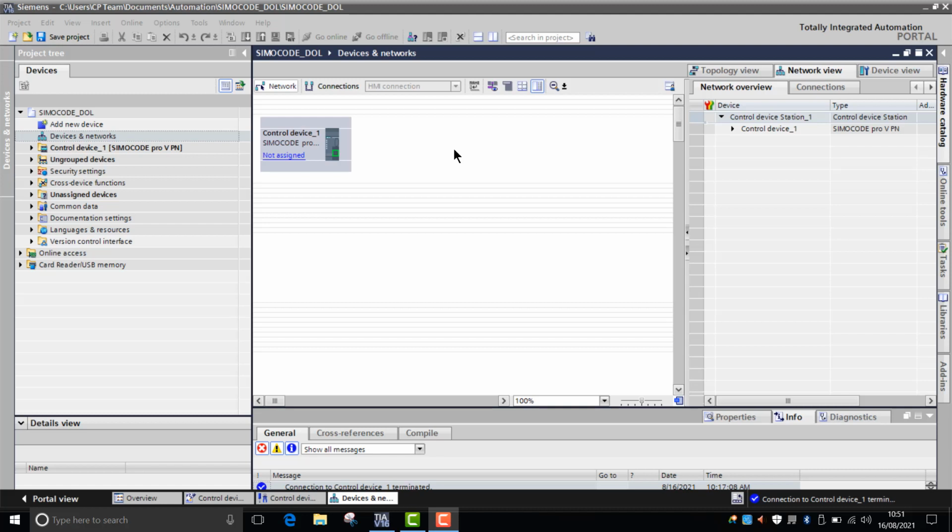Another feature is that the device also monitors hysteresis discrepancies in this feature. You could utilize that for an underperforming motor. If you have a discrepancy in hysteresis, you might have a low efficiency motor. You'll have low torque and a low power factor. All of those conditions are undesirable in a motor application. So I'm going to jump in now and show you the feature and how to access it.